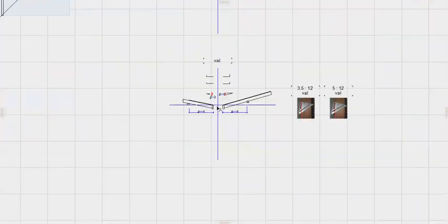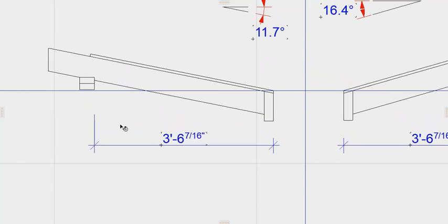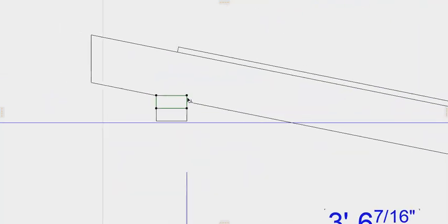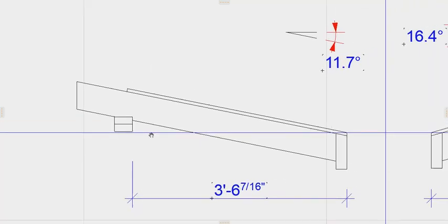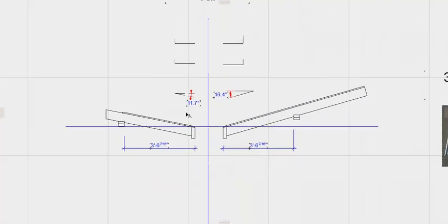If you're having a problem, you can also just snap out on the floor a plan view of your top plates like this and a plan view of your fascia. That way you know from here to here is 30 inches, and from this inside corner here to your wall, you'll know what that distance is if you just snap it out on the floor. And that's how you'll get that number right there, and that will give you how to align the edge of your wall here. And again, it's just 3.5 inches, and it's parallel to this line here, and the other side of it is parallel to that line there.